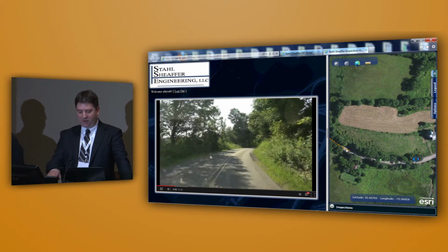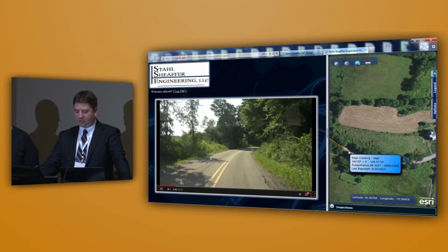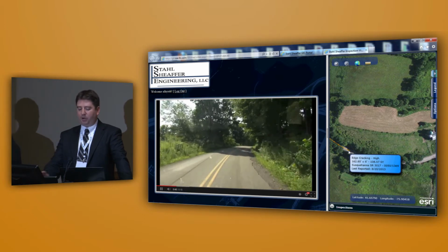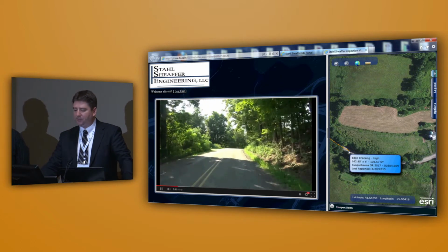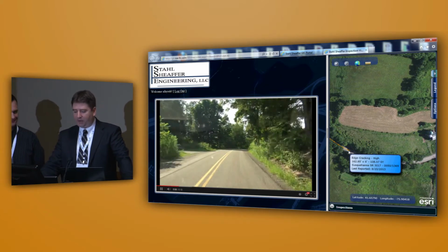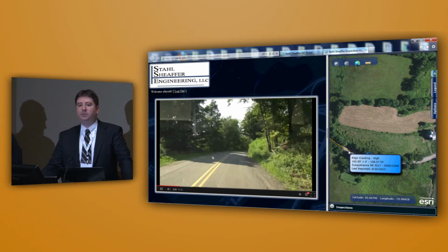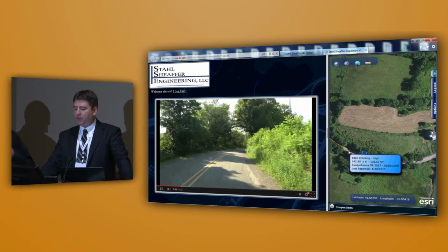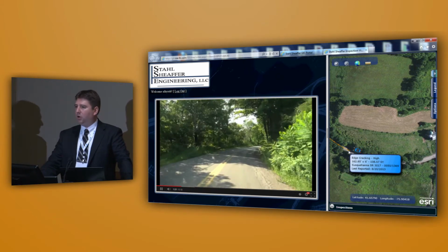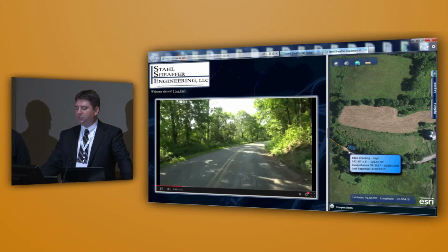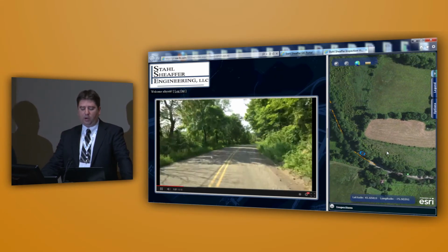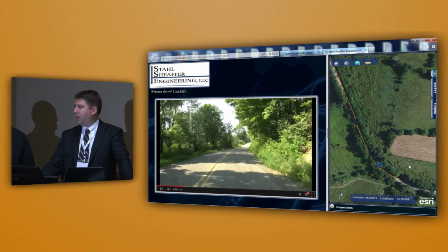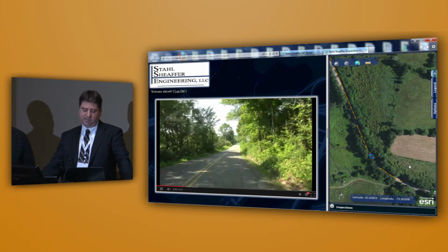But you can see as we're advancing along our video inspection route, we're approaching some roadway damage that was identified by a previous inspection. This is an area of high severity edge cracking. It's approximately 108 square yards in area, and it was previously identified on the August 20th inspection on Susquehanna County State Route 3017. We also display the segment and offset location in PennDOT's linear reference system.